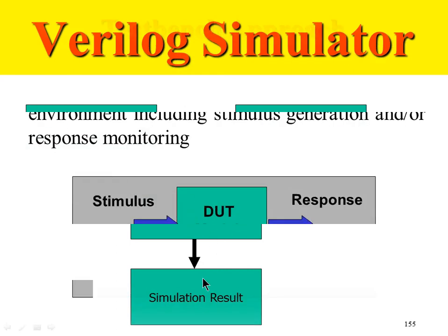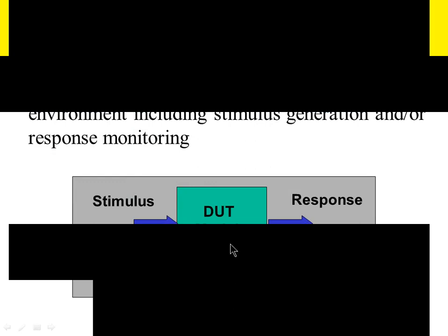So this is what you have. This test bench is another Verilog design, or Verilog module for that matter, under which we are going to instantiate the design under test. We saw structural modeling techniques, where we created small modules first, and those modules were instantiated under a bigger module, creating a hierarchical design. The same concept we are going to use: whatever the top level of the design is will be instantiated under the test bench module.